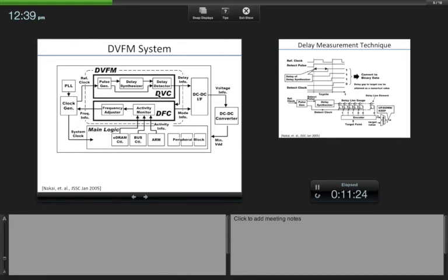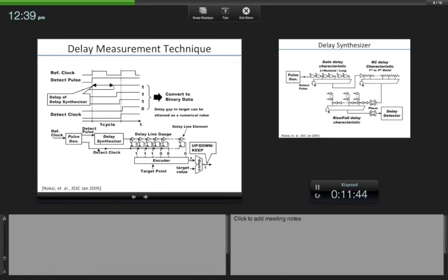And then you have the voltage DVC, dynamic voltage controller, which now goes ahead and identifies the right voltage to operate for that frequency, right? The lowest voltage where the circuit will operate correctly. So one of the key components there is this same delay monitor, which they are calling delay synthesizer. Okay, so the delay synthesizer's job is to synthesize a delay, which mimics the delay of the critical path.